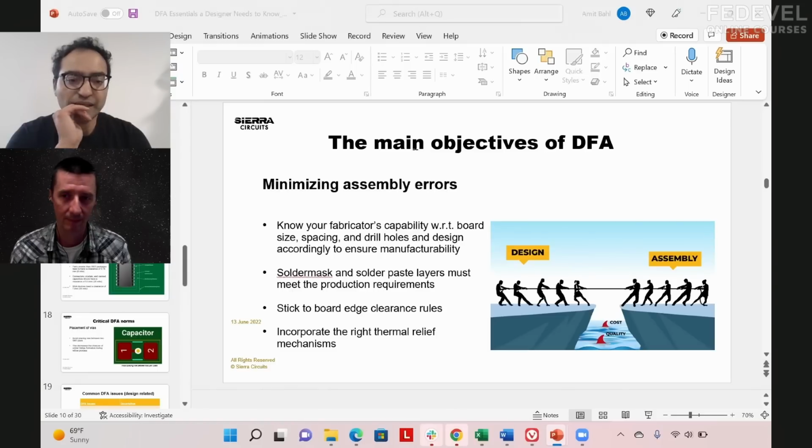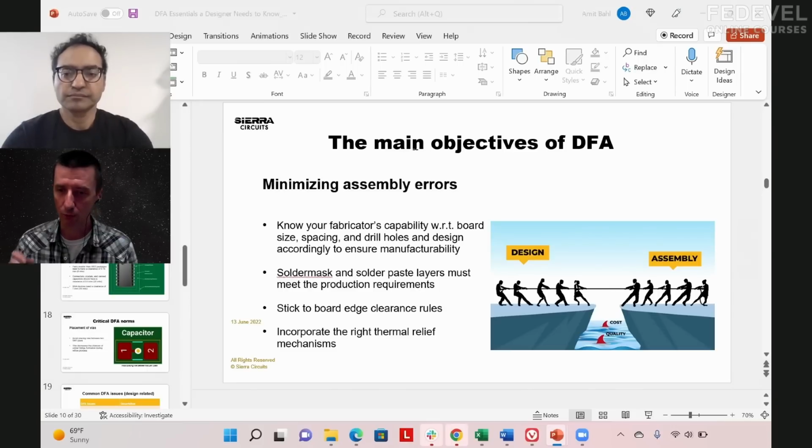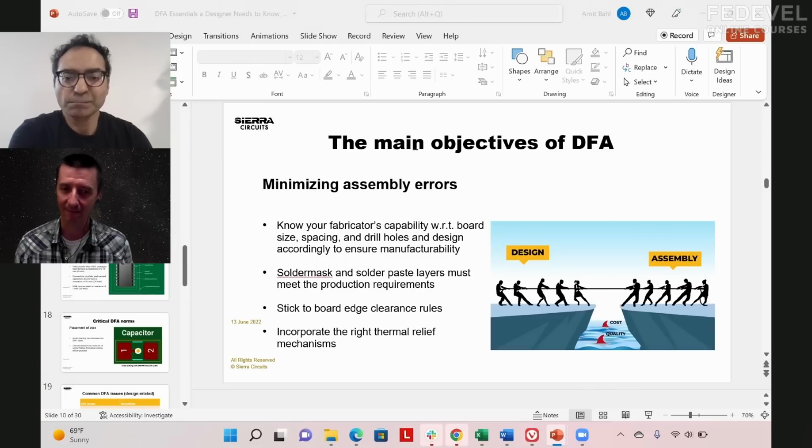What other errors are the most common mistakes? Then the next would be the wrong footprints. Yeah, incorrect footprints is a big one. I believe if someone is doing their job properly, that should not happen. For example, I learned very quickly that before I send a PCB to production, I should always also buy the physical components and check the footprints. Because if you don't do it, there is a very high chance that there is going to be a mistake in the footprint.